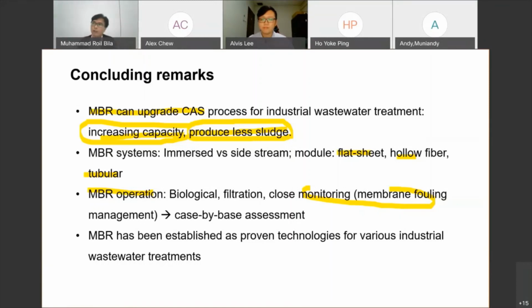And then of course your MLSS will go down a little bit, but MLVSS lower than design is probably less of an impact than when you have MLVSS higher than design. The problem won't be on the membrane. Your filtration will be as good at 6 or at 10, but the problem later on, when you have very thick sludge, will be maintaining the dissolved oxygen.